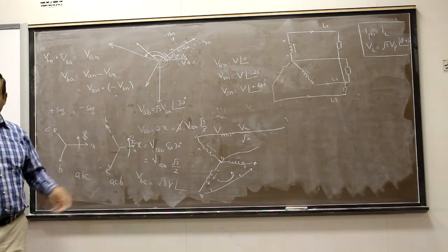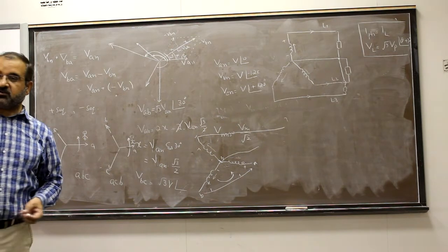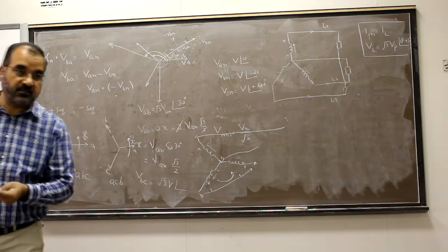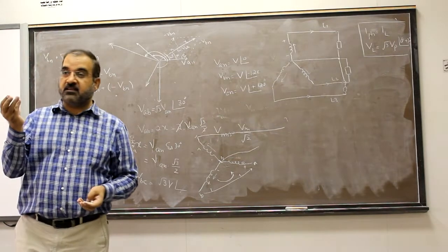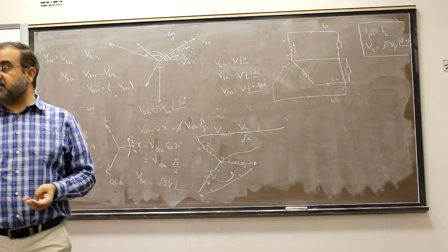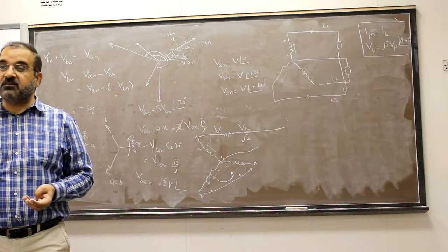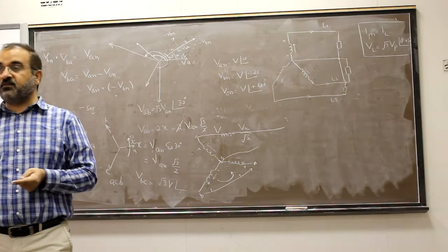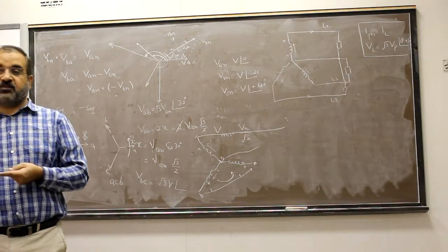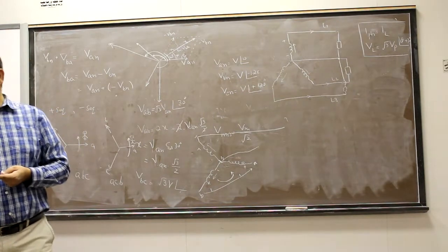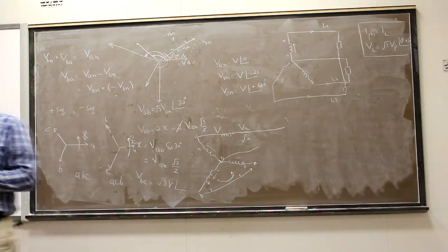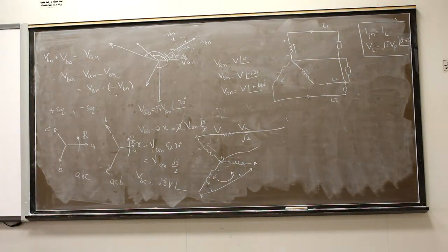So in a power system, students who studied with me before, I gave you that there are 4 conditions to satisfy before interconnection. Those 4 conditions are same voltage, same frequency, same phase angle, and same sequence. If any one of these 4 is not satisfied, you cannot connect the system. Voltage, frequency, phase angle, and sequence, all 4. Any one of these not satisfied, finished, no connection. But this is one thing.